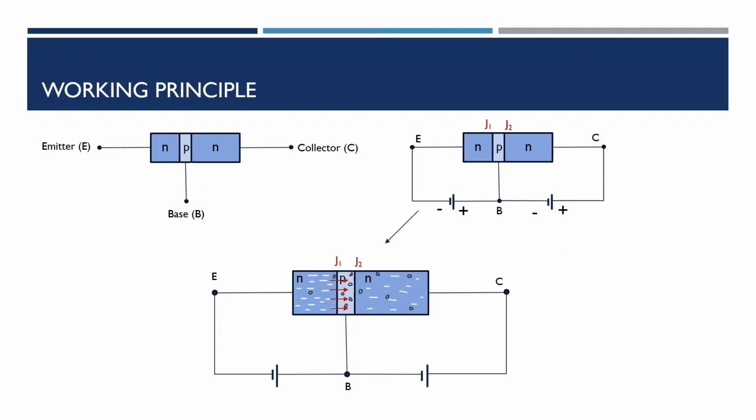However, since the doping in this base layer is very low, as I previously mentioned, and since the width is very low, there is a very low amount of recombination between the injected electrons and the existing holes in this layer. The ratio of electrons to holes is very low, so the electrons will not have any holes to recombine with. Because of this physical constraint, the electrons will mostly pass into the collector layer instead of recombining in the base layer. Some, though, will still manage to recombine in the base layer and then flow as shown.